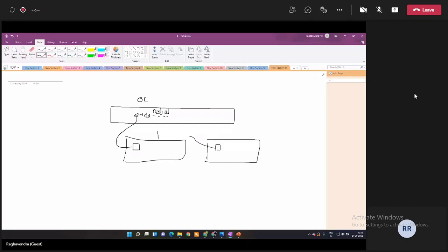Now, why this works is because this Octo Clock contains a single crystal. The crystal in the Octo Clock is again not perfect. It is not ideal. But since both the USRPs get the exact same reference, they are able to maintain the same clock rate and generate the same carrier frequency. Similarly, there is something called a PPS output, which is the reference that we provide for the ADCs and the DACs. So the references go like this over here. In a single Octo Clock, we'll be able to connect 8 USRPs.